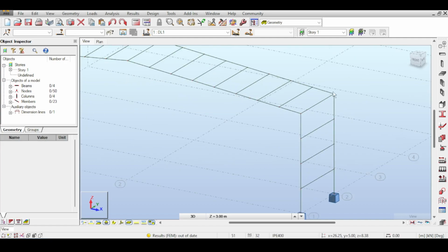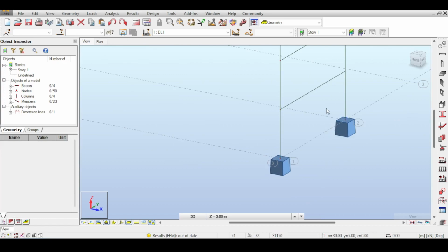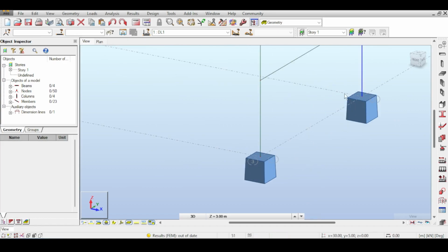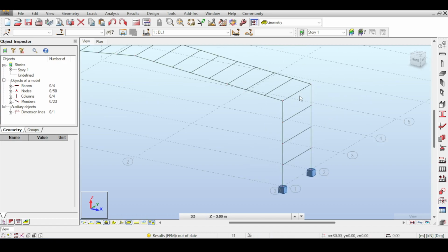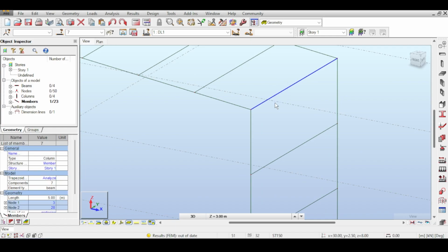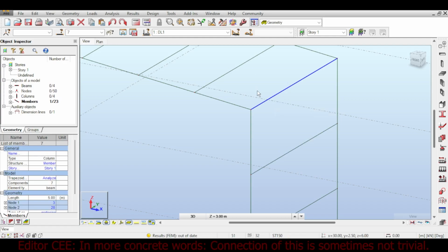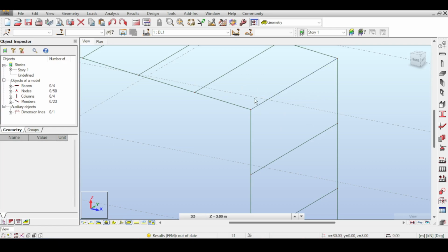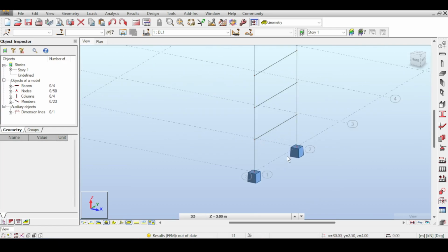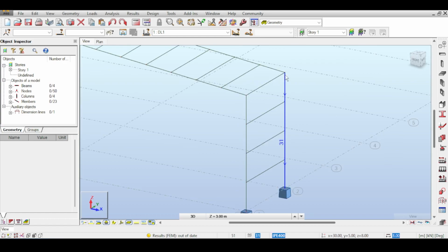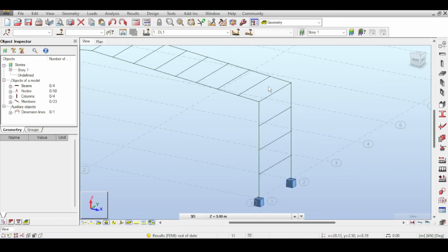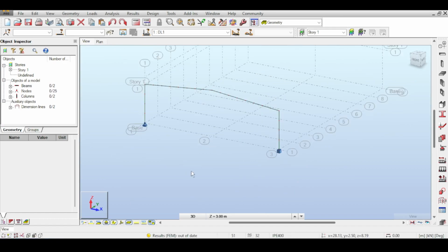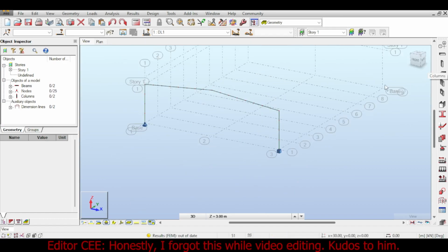This doesn't work. Why doesn't it work? Because the last cladding here is basically dug into the ground. You need to provide a purlin here. The purlin here is missing. Also, here you have one purlin that seems to be giving 2 claddings. And this doesn't work because your purlin is usually a C channel, so how are you going to fix 2 claddings in one purlin? So I think I need to add a purlin here, and a purlin here, a purlin here, and so on. So okay, let's Control-Z this very quickly. Wait, did I mess up my column? My error senses are tingling.